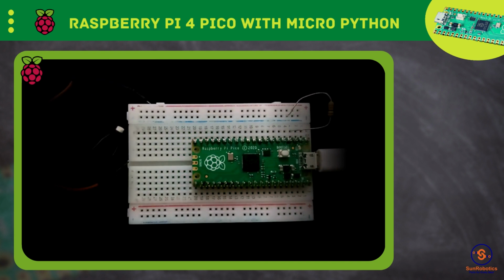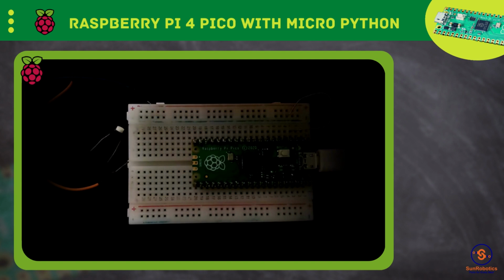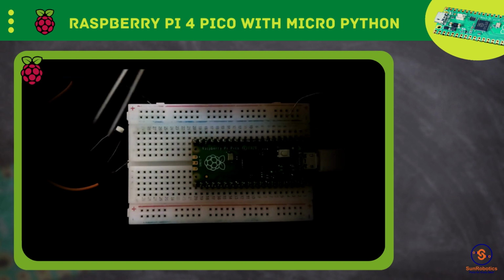Let's start. The resistor I used in the last project is kept over here. So there is a ground trail. Then I wanted to find GPIO 3. That GPIO 3 is actually the 5th pin position, next to the ground terminal. You can see the ground. The longer leg of the LED is positive and the shorter one is negative. We can say that is the ground one.